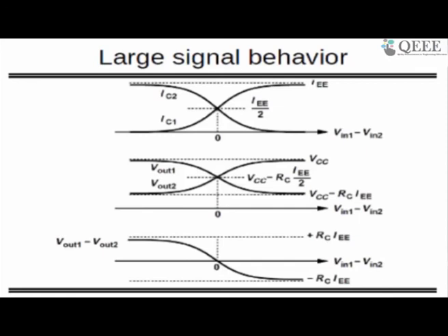look, most of the time, if it is a communication application or any other application where you are sending some signal, it will not be linear always, or you can say it will not follow the linear equation y equal to mx plus c. It will always have some non-linearity, or it will have harmonics, and you don't want those harmonics. Those harmonics are measured in terms of signal to noise ratio or the total harmonic distortion. So if you want to reduce them, you should always use differential structure, nothing else.